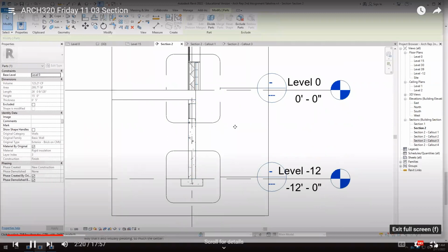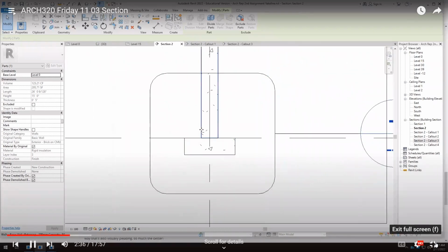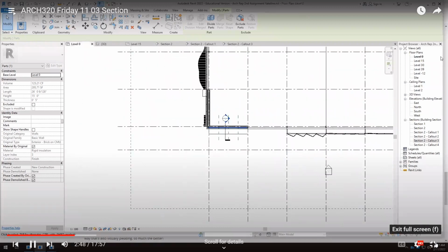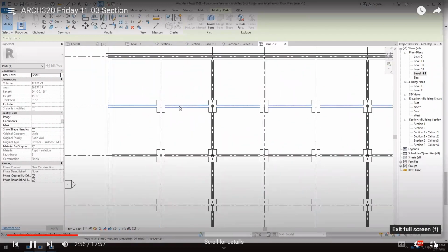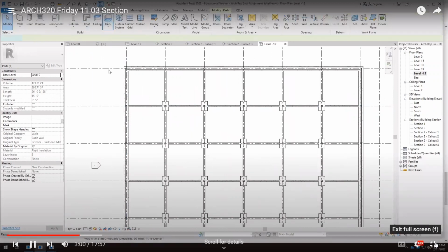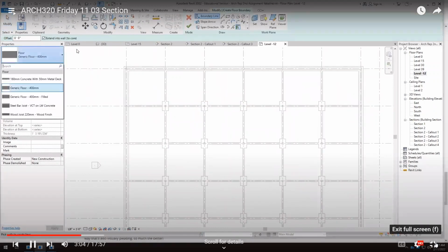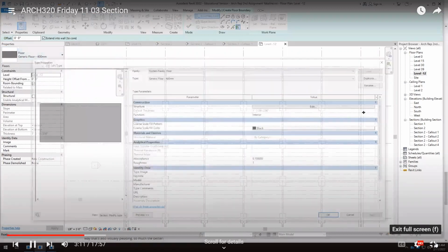And something else that we have to do, we have to increase the quality, the thermal performance of the building by preventing thermal breaches from happening. So we have to make sure that the thermal insulation is continuous. So when we are creating a floor or another detail for a wall, then we have to make sure that we have thermal insulation, continuous thermal insulation around the envelope of the building.